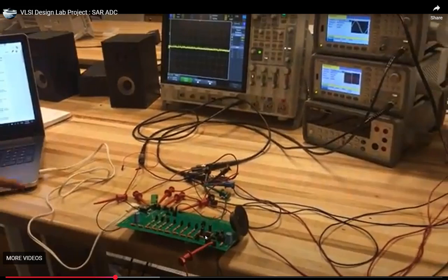So what's happening is they use a music signal from the laptop or your phone, doesn't matter. They have a jack header connected to it and split the two wires, because of these two wires, one is the analog signal, one is ground, and they split them and plug. Oh, they didn't, because they use a jack header here as well. It's an audio jack. So eventually plug it in and split the signal on the PCB. So that's the analog output, keep in mind. So from the speaker here, it's an analog output.